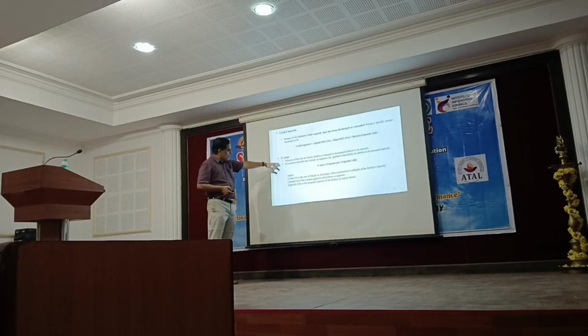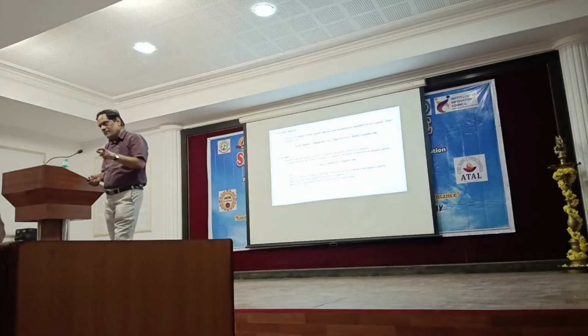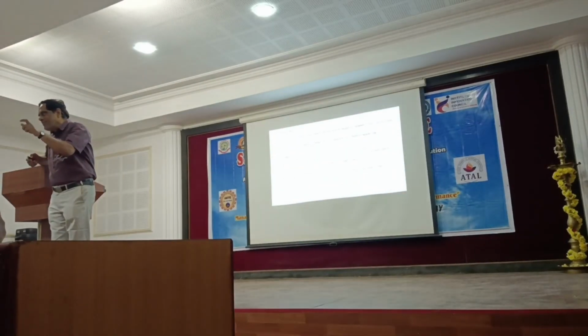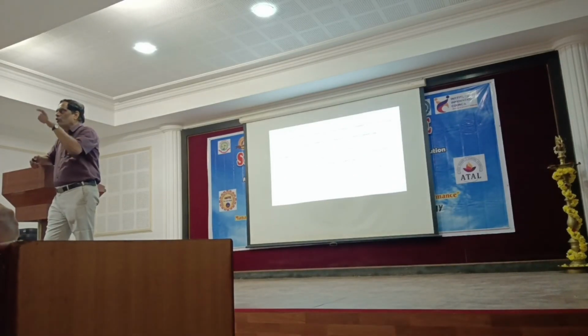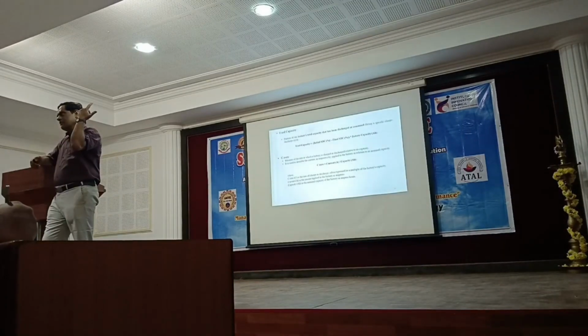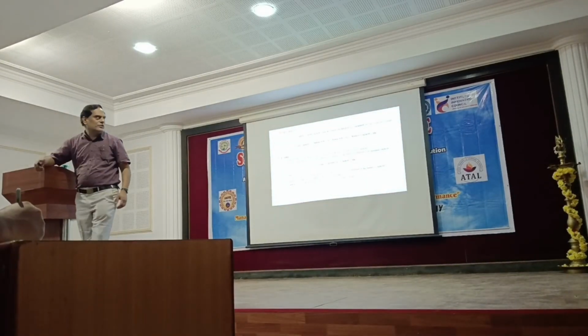Used capacity. I already mentioned C rate, 1 C rate, 2 C rate, 3 C rate. If we want to know the rating when you buy a new battery, I should know at what rate it can work well. Can it afford to do quick charging when you go for 2 C rate, 3 C rate? Already the technical specialist should decide. Normally, we use 1 C rate, but during charging, if it is able to take care of 2 C charging, they design appropriately. Otherwise, it takes a few hours and so on. Normally, we take 2 or 3 hours. The battery pack is less expensive, cheaper, but we cannot do very quick charging, because of the way the battery pack has been designed actually.